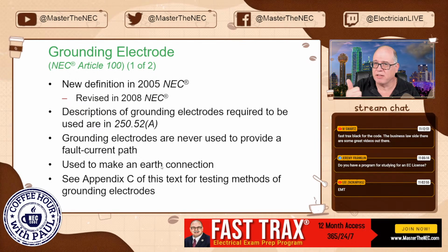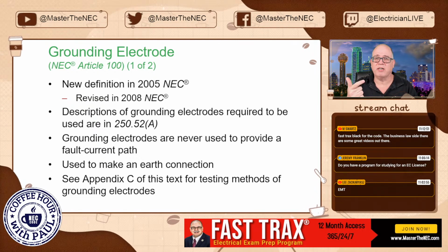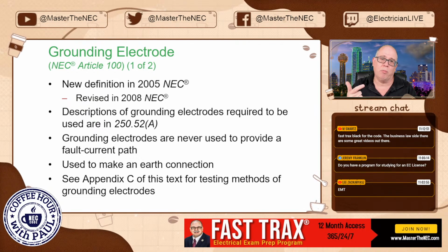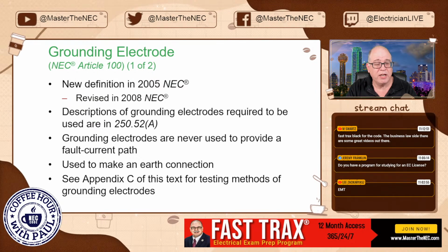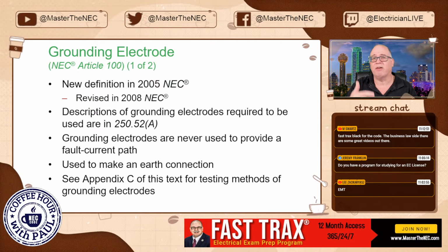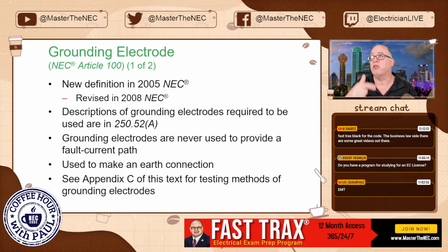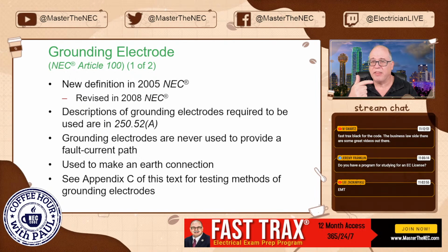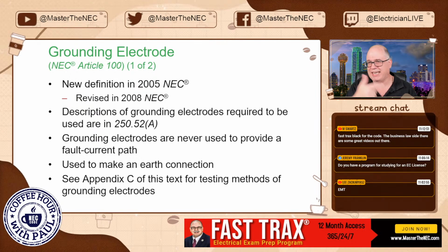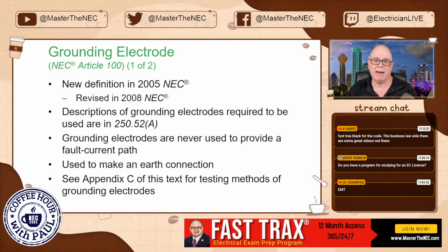One, stabilizing the voltage. Also, you could have high power lines come in contact with low power lines on the supply side, and we want to give it a path to earth, because the utility can use the earth because of the level of the voltage they use on the primary side for the utility lines. Do a little Ohm's law, and you'll see how that works out. They do use the earth. We cannot use the earth for our applications.